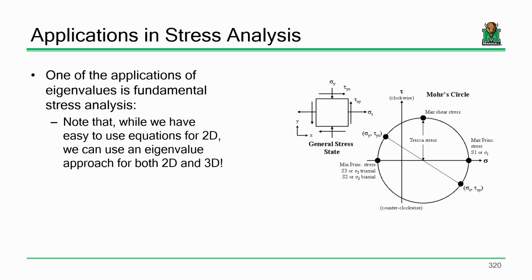One of the nice things about eigenvalues, especially in a stress analysis problem, is you can apply the same procedure for 2D stress and 3D stress, and it works across the board. You could theoretically do it for 1D stress, but it stops being stress analysis at that point because there's just one stress and that's it.